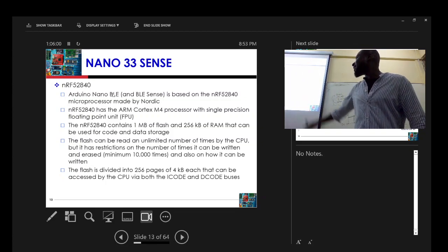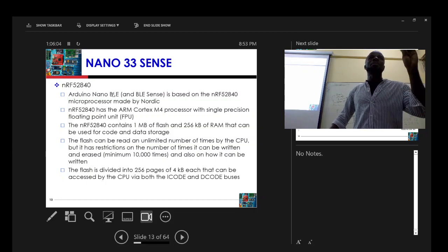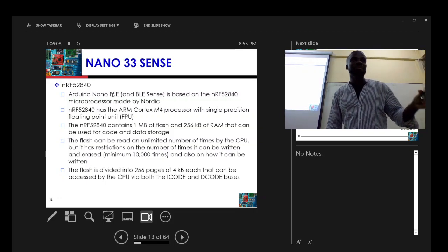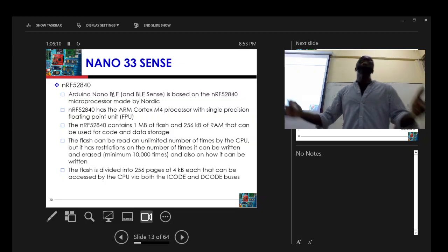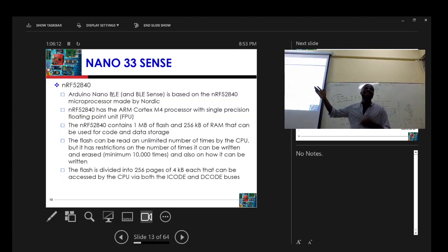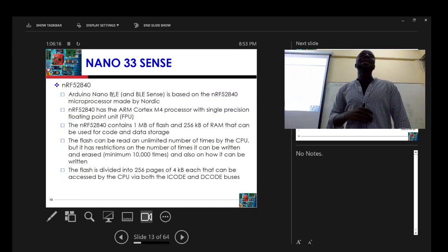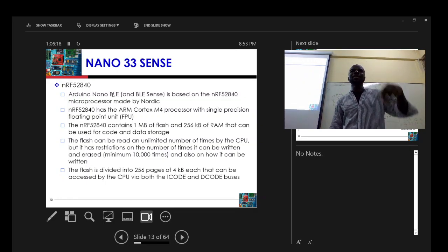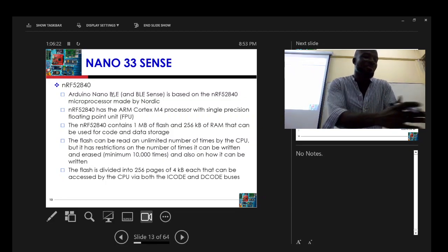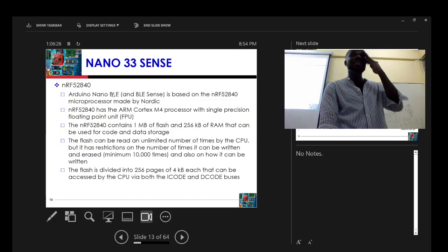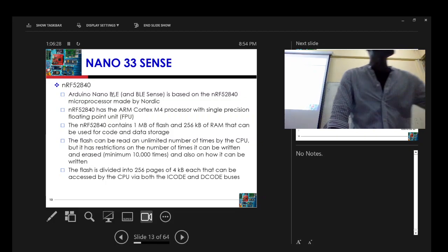So it means that if I upload codes 100 times a day, how long will it take to last? Just easy maths. I have 10,000 times I can upload codes, right? And then I upload 100 codes a day. How long does it take before the flash gets damaged or degraded? 100 years.